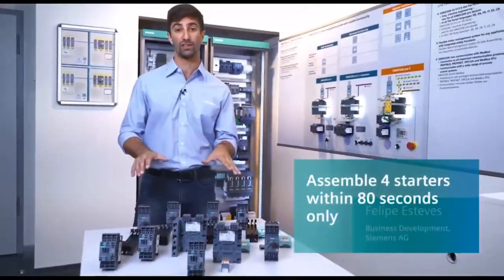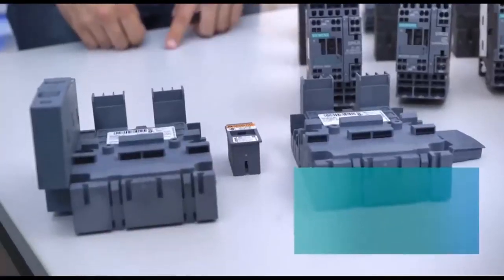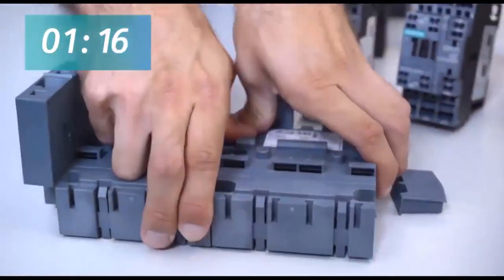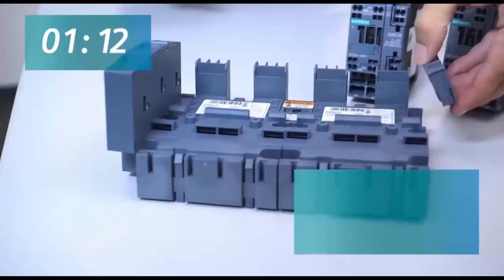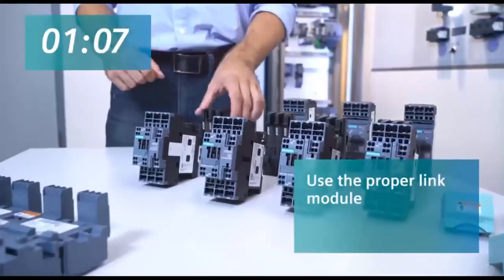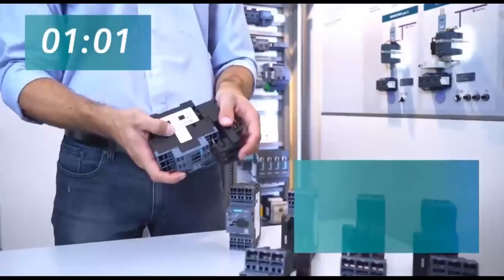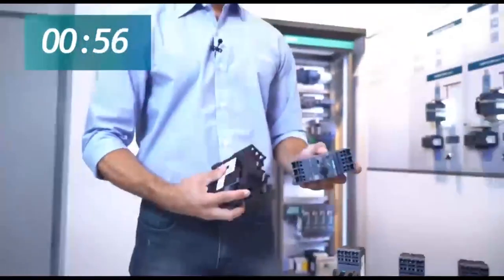We are now going to watch a short video to show you how easy the system actually is. My colleague will show you this. Only my two hands used as tools, I will assemble now 4 starters ready for control connection within 80 seconds only. First, I will assemble the base to accept 4 starters using the expansion plug. And to remain finger-proof, don't forget to use the end cover part.